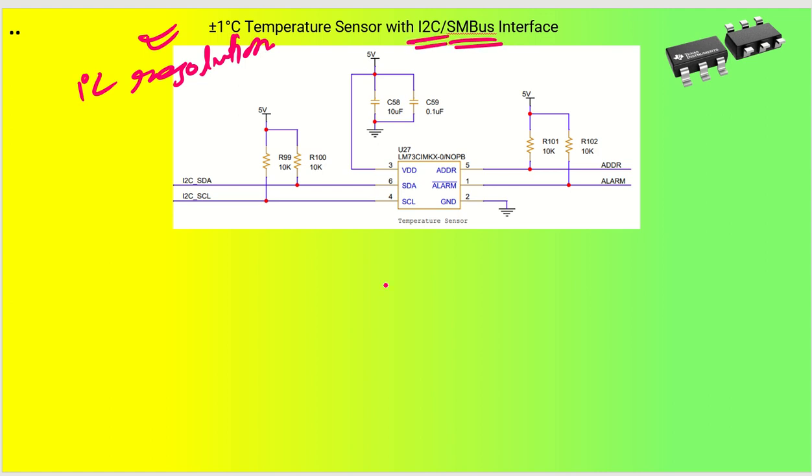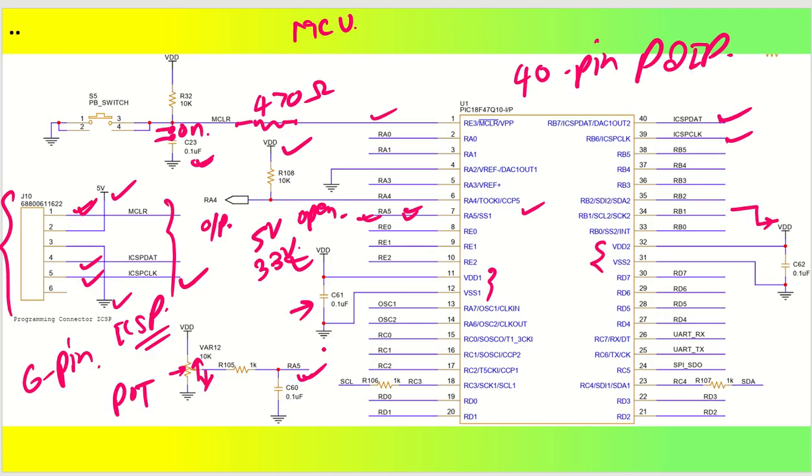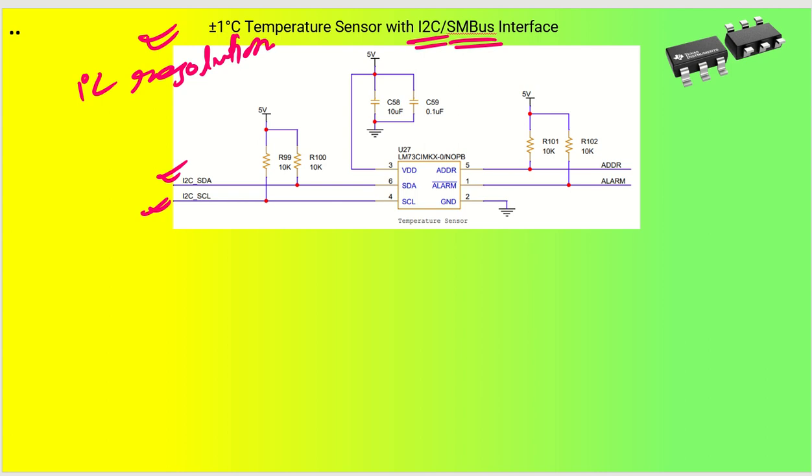So what I have done is I have put an I2C interface. The I2C SDA and I2C SCL lines will be connected to the microcontroller pins, which I'll just indicate for you now, and then we'll see later. So you can see SCL and SDA. You can rename these I2C SDA and I2C SCL, so that you can connect these lines to these particular pins. So this is how it will get connected, and I have kept pull-ups here, so there is no need to pull up near the microcontroller. Here only I have put it, so that the respective peripheral makes sure that I2C is taken care of.